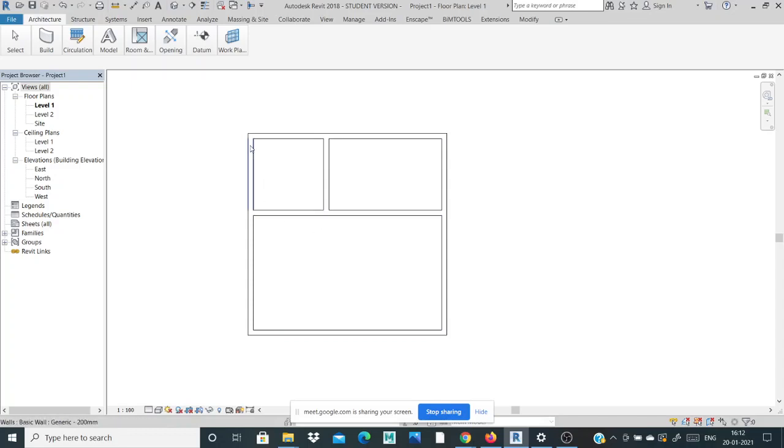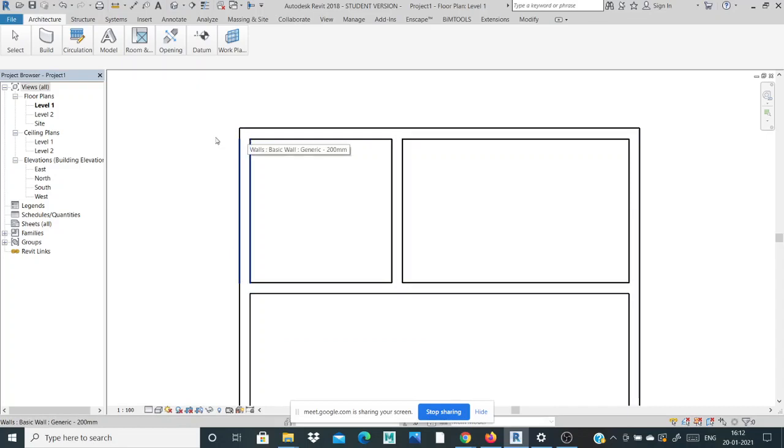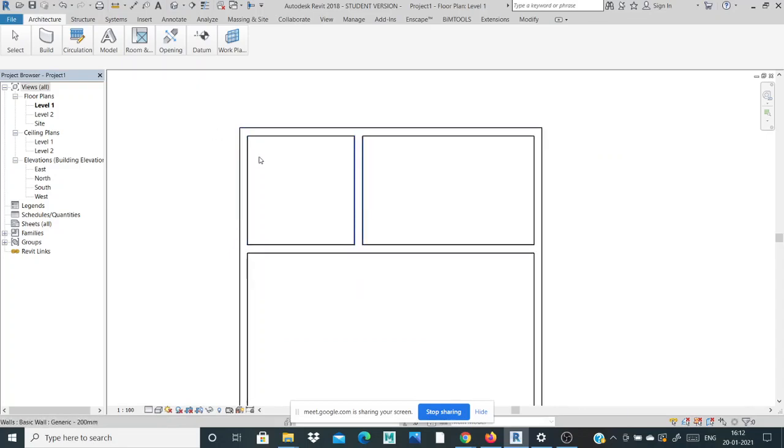Then how to calculate the center to center distance? You will go for any software or manual method. Do not take the end to end distance. This is totally wrong. You go for the center to center distance. That is the correct one, right? In practical construction fieldwork, you take the center to center distance, right? This is the correct manner.